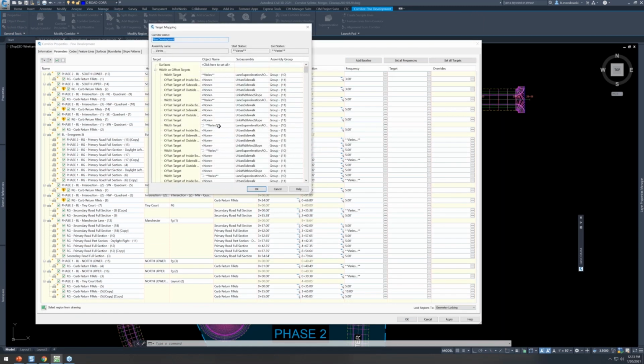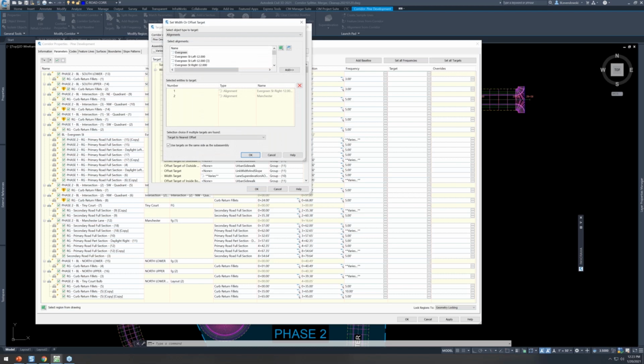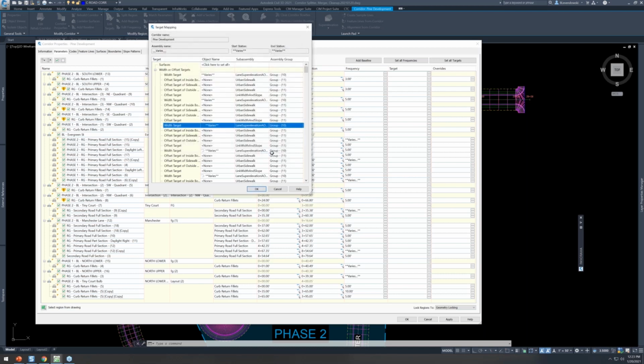You have to assign all these polylines and feature lines and alignments and profiles to control varying lane slopes and lane widths, all sorts of different things. And it's a very tedious approach on how you assign that. And we've got a really powerful tool called Corridor Mapper that aids with the assignment of that stuff. But oftentimes, what we're after is simply kind of a reset or a nuke button on a portion of our corridor, or even all of our corridor.